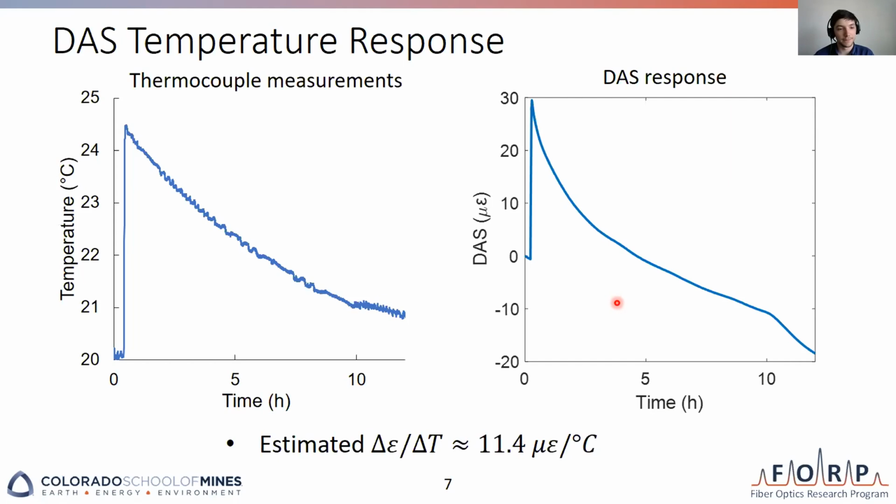A question from Rob: are the fibers in this experiment polymer or polyamide coated? That's an interesting question. I'm probably not aware of that. I should say that for SMF28 from Corning, the bare fiber was used. But for some experiments, I used Luna fibers, which are special sensors. They look like bare fiber, but they can experience relatively strong bending forces. I think this was polyamide coating, because it's not transparent, it has a yellowish color. So I guess this was polyamide, at least for these Luna sensors. For SMF28, I'm not sure. I could check that.